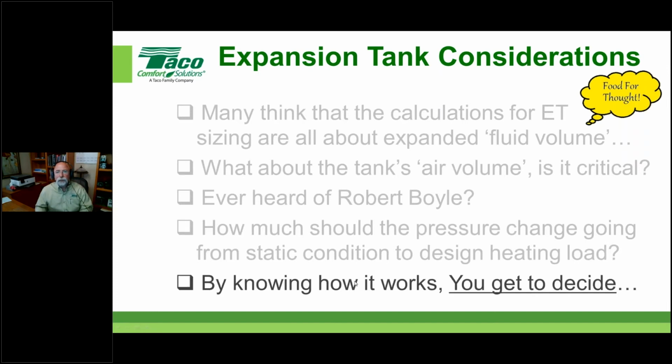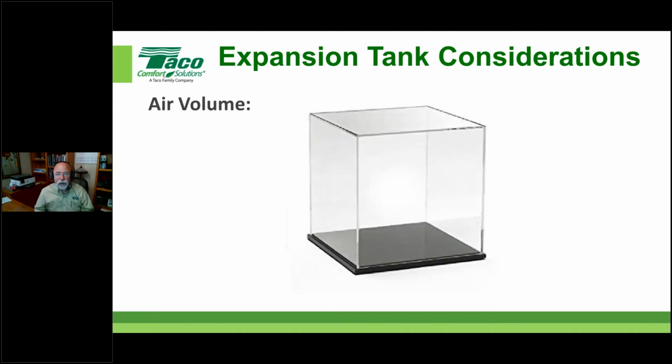The cool thing about sitting through a session like this and having a better understanding is that you're in charge of that. You get to decide how much that pressure is going to change merely by sizing the tank more appropriately. So let's talk about air volume, since I've already told you that's actually more important. We need the ability to receive that expanded fluid. So it's all about air volume.